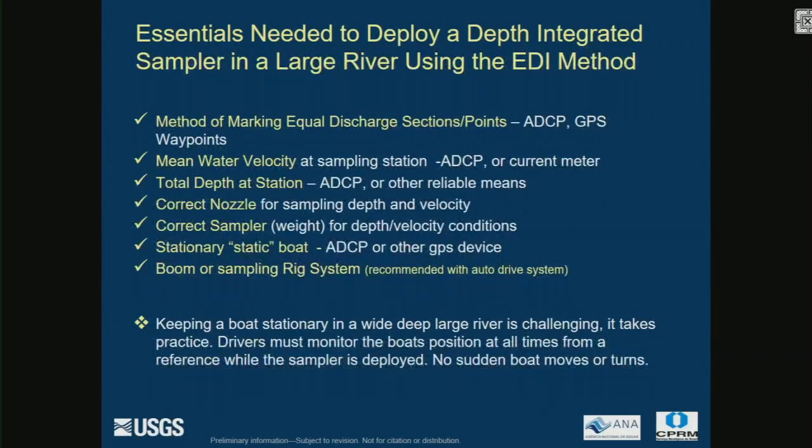So the essentials needed to deploy a depth integrated sampler. You need a method of marking the equal discharge section points, ADCP, a GPS to mark waypoints that's fixed on the boat. These are fairly cheap nowadays. The mean water velocity at the sampling station. Of course, ADCP,